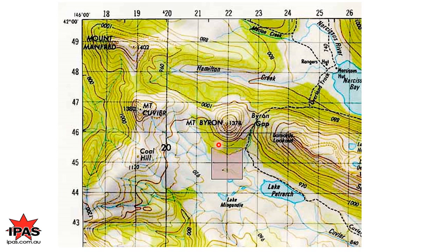Looking at the map itself, let's have a look at some of the information. Well, the green represents green vegetation. You have dark green along here, and then light green, indicating the vegetation is not as thick in the light green areas as it is compared to the darker green areas. And then you have areas like this which have virtually no shading, and that indicates that the vegetation there is quite sparse, may only be grassland. We have your typical contour lines, and by convention they're usually brown. Cultural features or man-made features, things like these tracks, the ranger's hut here, and other information of use, which we'll describe later on.